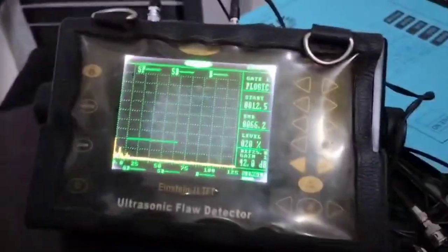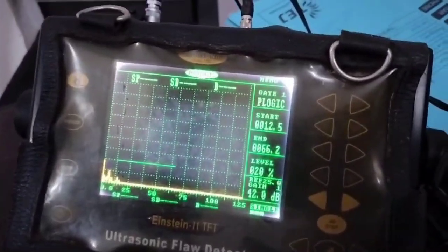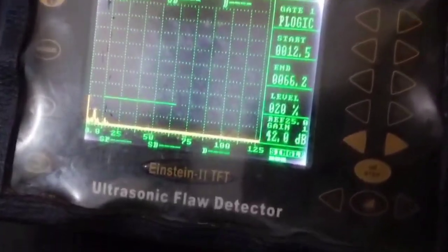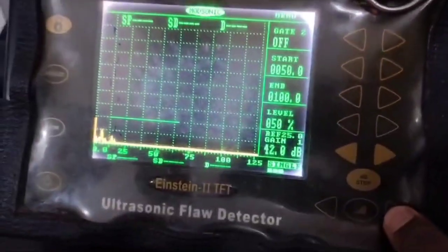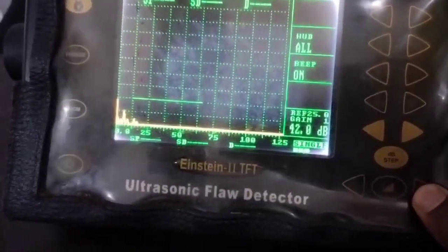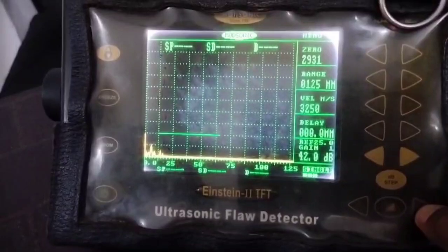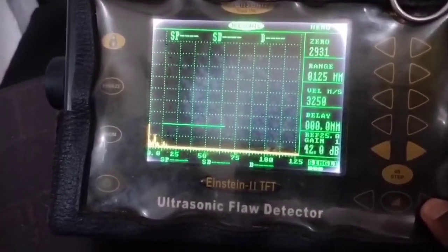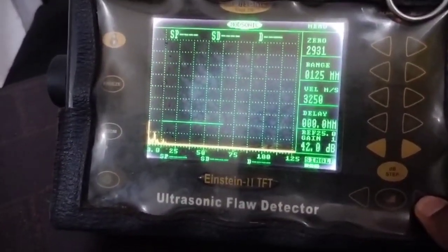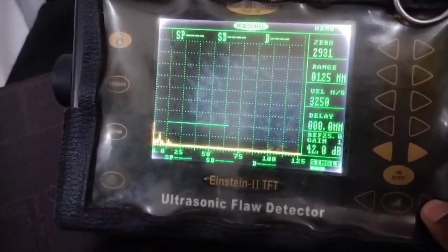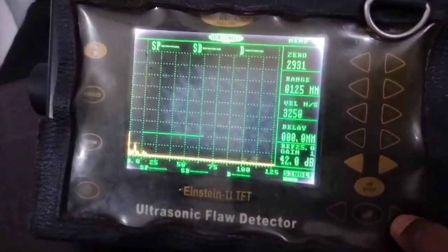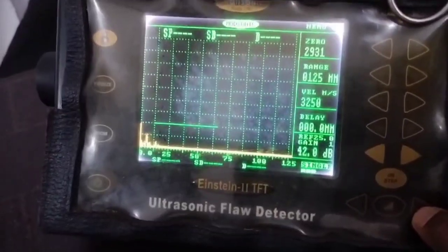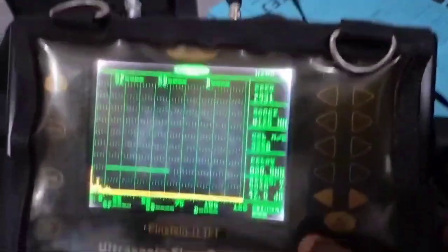To draw the DAC, we will go to the range, as we have a requirement of range. Here it is only 10 mm. If we calculate this, the maximum half beam path will come to 14.4. So the full beam path will be 28 point something, 1.5 beam path will be approximately 42, and the full beam path will be approximately 40 plus 16, that is 66. So according to that, we are using the range here as 100.